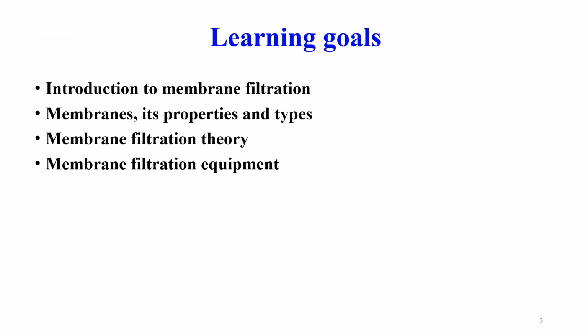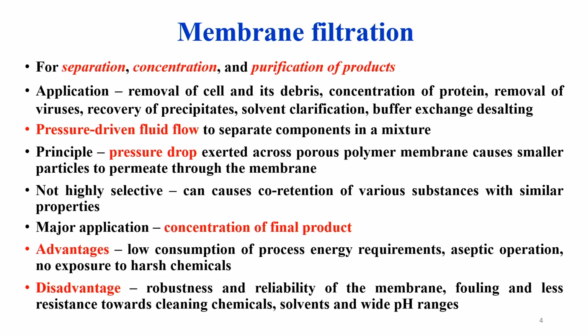So, today we are going to discuss the basics of membrane filtration, what the different types of membrane are, what its properties should be, what the theory of membrane filtration is, what the driving force is, what the resistance is, and then we will see the different types of membrane filtration setups. Membrane filtration is also part of downstream processing.